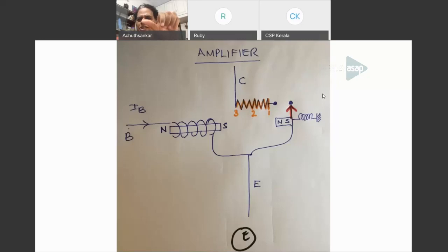So you carefully start increasing. At a particular point, you find that the water starts flowing from that water tap. Now increase it again, carefully watching the position. The water increases. Now after that, you start reducing. And you reach the point where the water started flowing. It doesn't stop. That is the interesting thing. It doesn't stop. So you go a little bit behind that, only then the water flow will stop. This is the holding and latching current of the water tap.